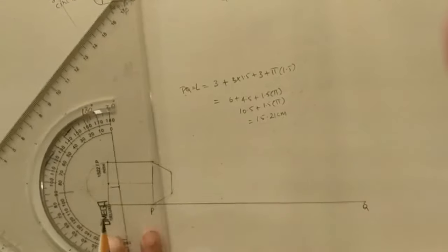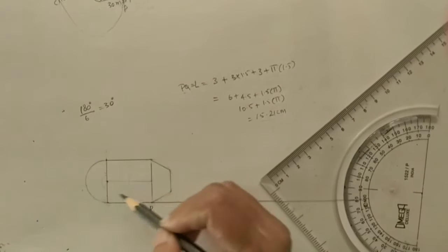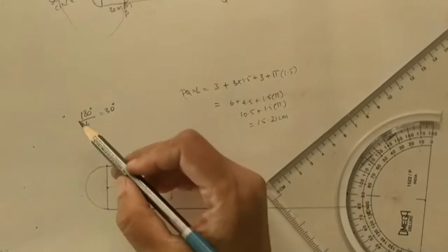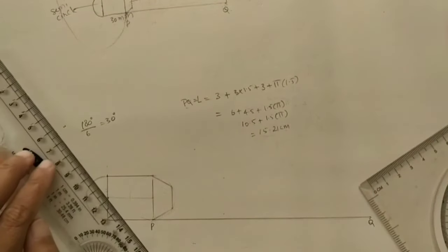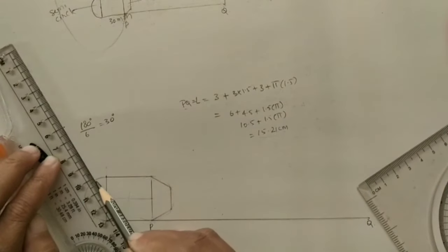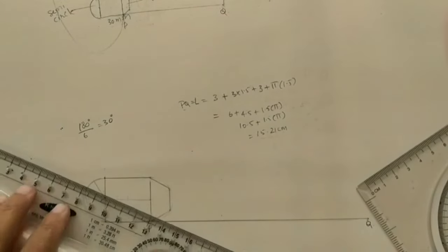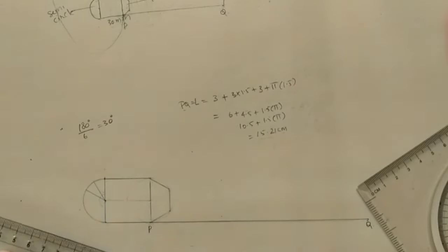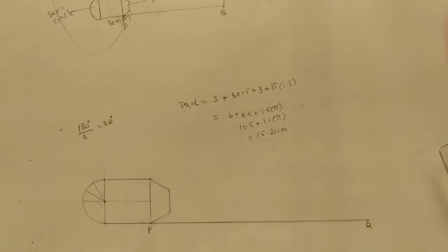Now join all these points to the center and draw the lines within the circle, so that we will get the divisions. Initially take this point at 30 degrees and join it to the center by using the scale. So draw the line within the semicircle. First part. And next point, join this point to the center, draw the line, and here this line. Already we drew the axis line here like this, and next point here.